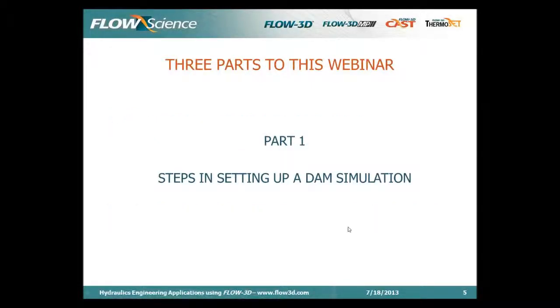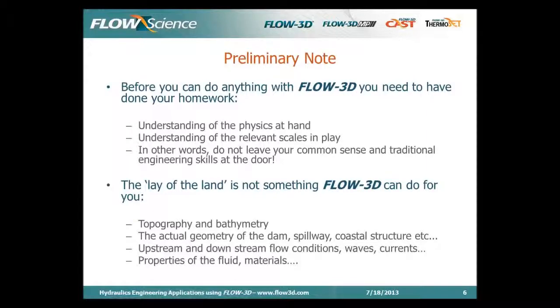Okay, so part 1. Before you even open Flow 3D, there are some preparations to be done. Flow 3D will not figure out the engineering fundamentals for you. You need to understand, from an engineering standpoint, the physics and scales and matter that are relevant to your premise. You need to know what you are trying to model, and you also need to know what I call the lay of the land, so topography, upstream flow conditions, etc.